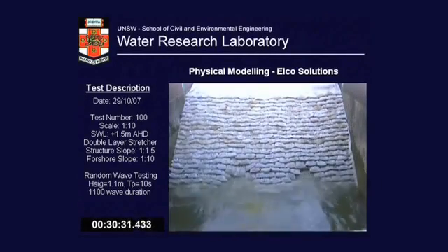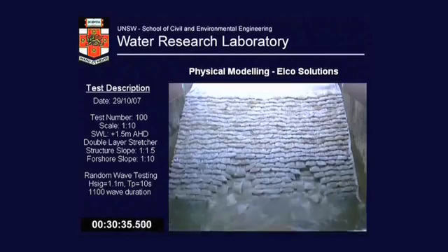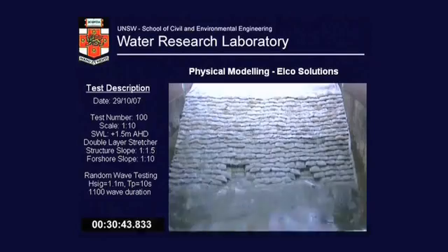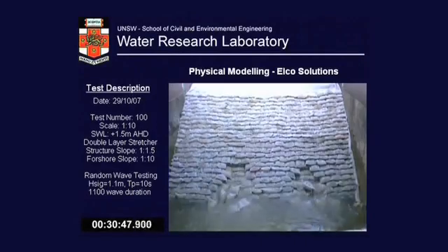And realise the aim of physical modelling is we have to test things to destruction or damage, otherwise we never know what the threshold is that the damage occurs. So that was an example of physical modelling, and that's how we generated the design curves for these structures, and I've got some examples of that later.